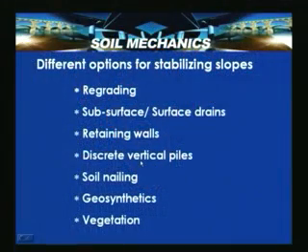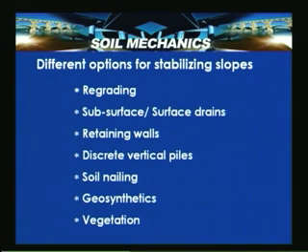In this method, the load arising due to the moving soil mass is transferred to the piles and into the deeper stratum. This method, discrete vertical piles, can be adopted for new construction or for an existing, predominantly soil slope, where it can be used for stabilizing the existing slope. Another technique which is gaining momentum in the recent past is soil nailing.